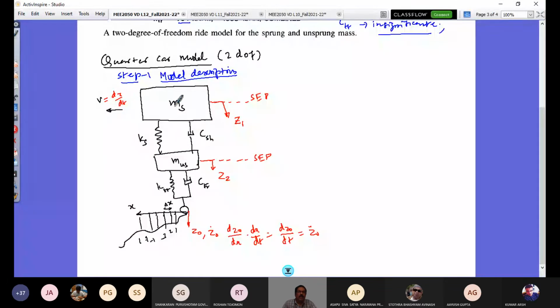So now this is your physical description of your quarter car model. And this is to understand the bounce. So in the Z direction only, displacement amplitude would be there, the bounce motion of your unsprung mass as well as sprung mass. And with this model, you would appreciate that the design of the vehicle always plays with these masses and the stiffness values appearing in these diagrams. So that is what is going to make a good isolation by default design of any passenger car.